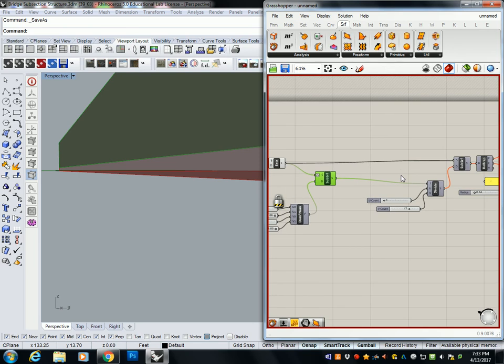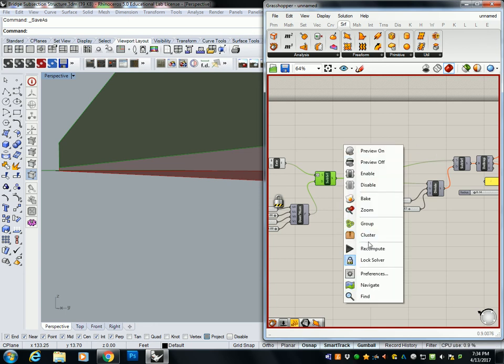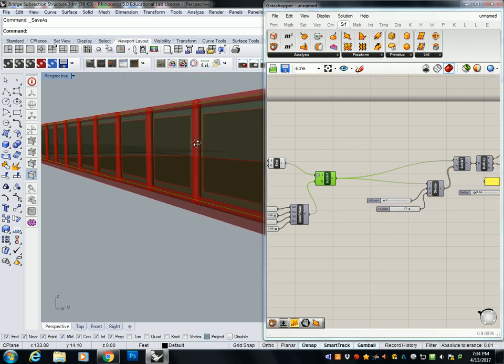That way, when I plug in Subsurf down here, that's my new surface, it's not trying to compute a subdivision on the new surface, but then reapply the actual application of that subdivision onto the old surface. Does that make any sense? So anyway, you just need to reconnect both of those and then turn off Lock Solver and it'll run again.